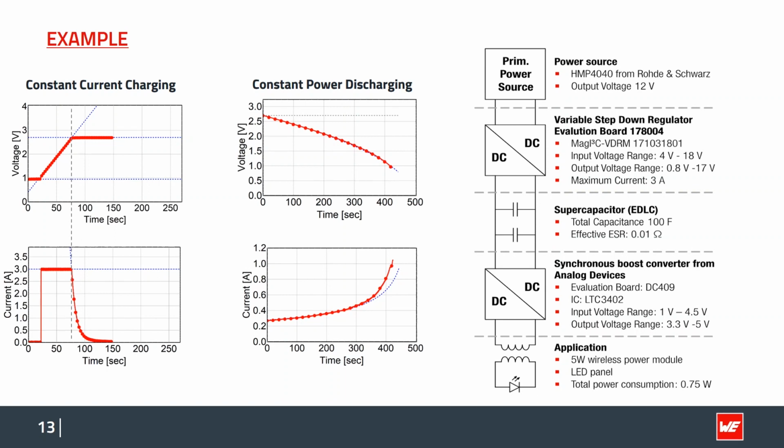The measured power drain is actually larger than the calculated one. This is because the converter becomes less efficient at lower input voltages. The calculations assume, however, a constant power loss due to the converter, which is of course only an approximation. It shows that it's always good to also make practical examples at the end, and that calculations can only be an approximation at the end. However, all in all, it fits quite well, I think.